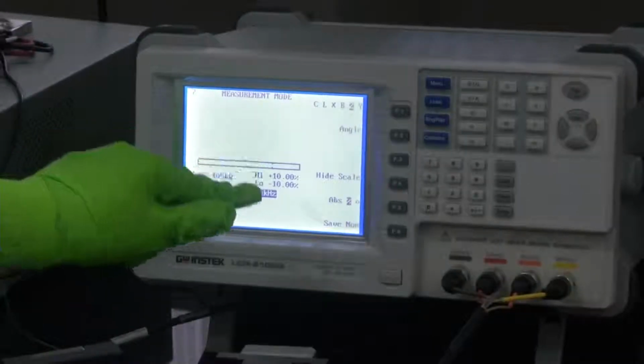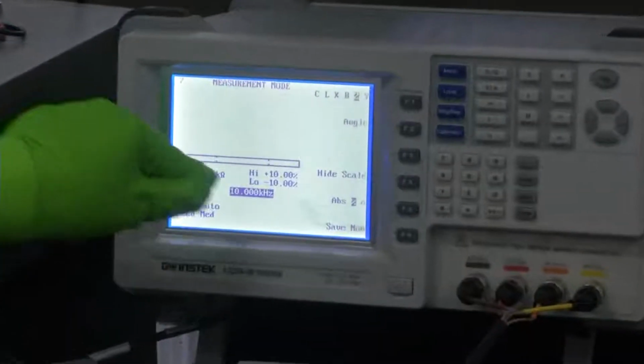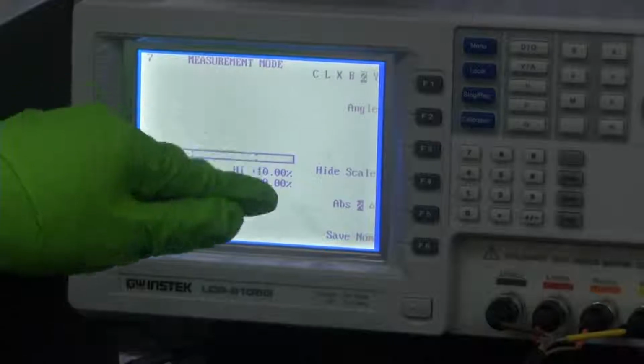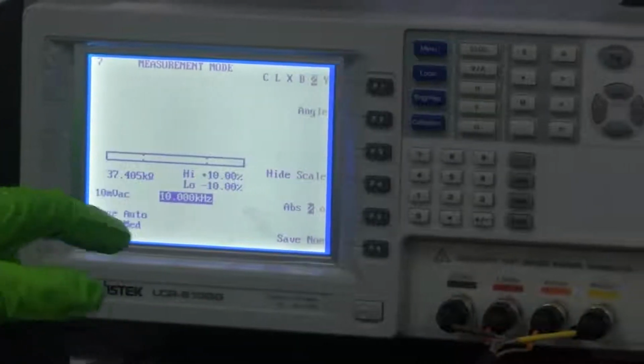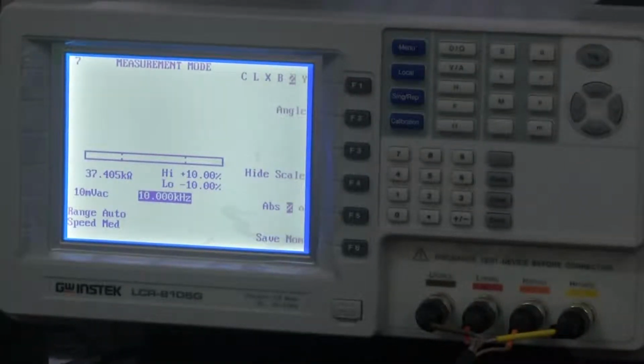So you could choose the options for the applied voltage and the frequency setting. All of this once performed, let's see after calibrating the open circuit and short circuit, let's connect this to the impedance analyzer, the sensor which we have here, and do the measurement.